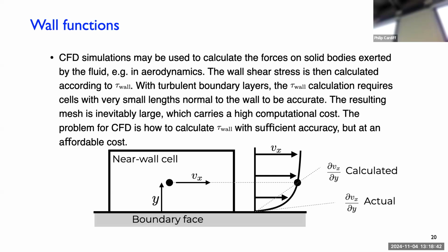And this is our first cell. So if we wanted to calculate the shear on this surface, the force going along this surface, we know that the formula for the wall shear stress is equal to the viscosity times this gradient. So if you plot the velocity going away from the wall, it's 0 here and then increases. If you take the slope of that right at the wall, multiplied by viscosity, that's the shear stress at the wall. That's the definition for a Newtonian fluid.